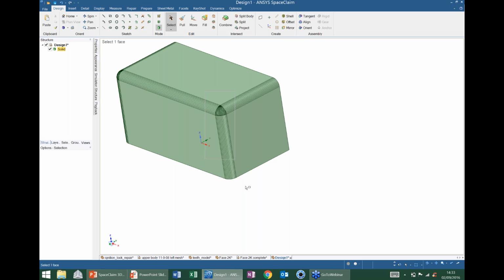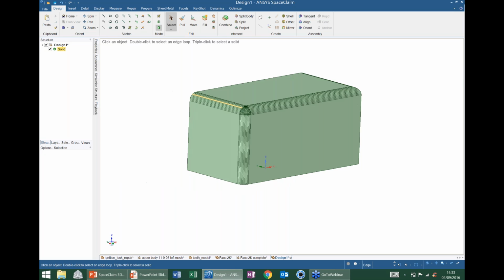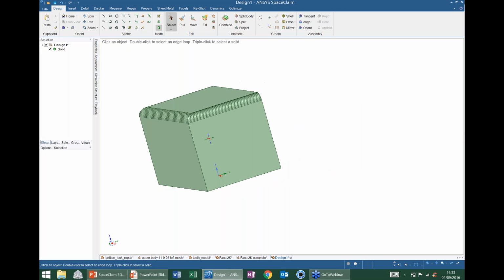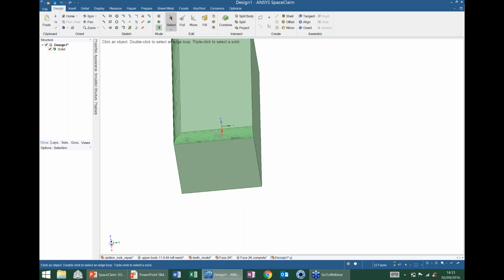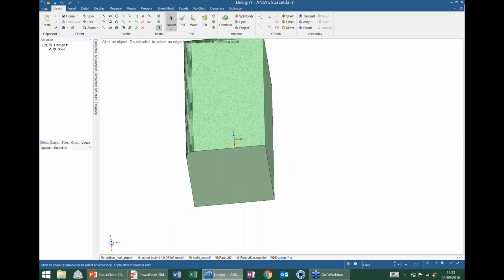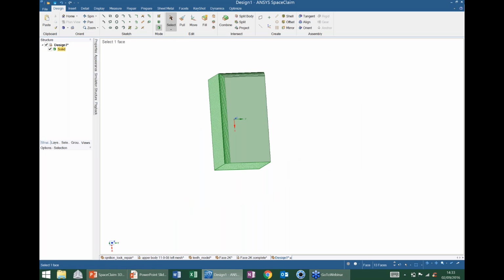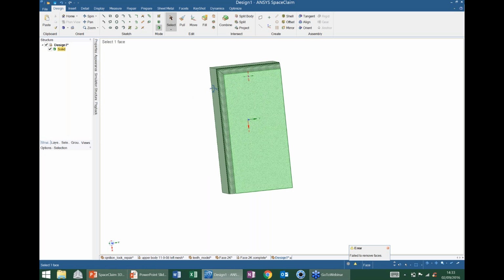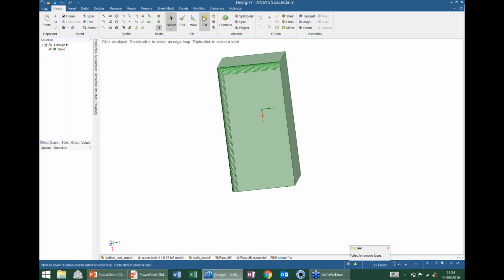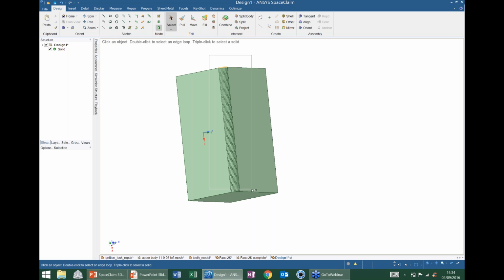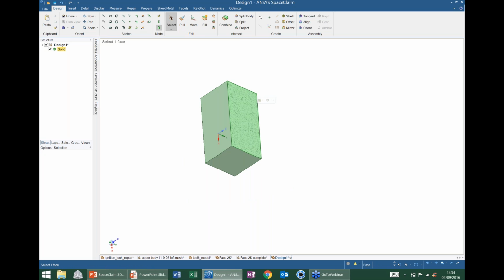So using the fill tool, I can just grab over an area and fill that, and if I grab over another here, I can fill it. And then what we can do is just fill in these poor faceted edges and create a nice smooth round. We can just remodel in the rounds. So we've got the same shape from the STL, and we can bring these in.